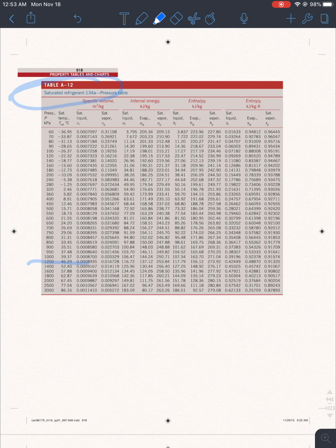We don't know the heat out, so that's why. So here's equation 1. You don't know the heat out, so find the heat out. There's the equation for it. Use the enthalpy of the water at each of the points. Here's point 2, here's point 1. And you find the enthalpy inside the tables, inside the steam tables. So let's go over to the steam tables.